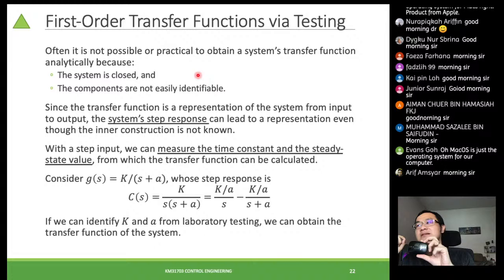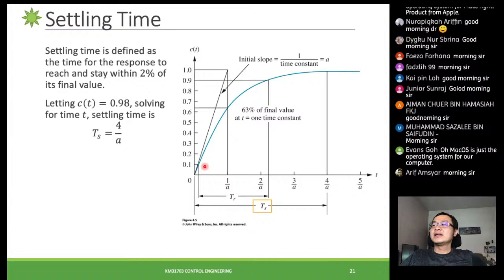So you give a 1/s signal to it, maybe a kind of position movement, and you capture how fast the cursor actually moves from one point to another. You plot it into a curve, a graph, right? From this curve, you can reveal the time constant. From the time constant itself, you can know the settling time and so on.